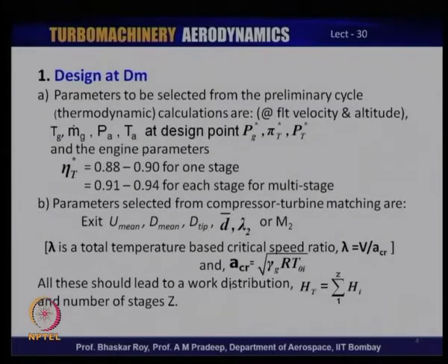And then from the cycle analysis, we have some idea what should be the turbine pressure ratio prima facie, to match with the compressor pressure ratio to supply the necessary amount of power that runs the compressor or any other load like propeller or fan.